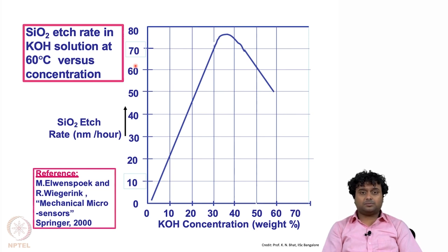silicon dioxide as a protective layer. Let us say we need to etch for 10 minutes for 1 micron of silicon etching. Then in those 10 minutes SiO2 will get etched only like 5-6 nanometer, right, only 5-6 nanometer of SiO2 will get etched in those 10 minutes. So, that much of oxide layer is good enough to protect the silicon layer, because the SiO2 layer will protect the silicon until it itself gets etched by the KOH.